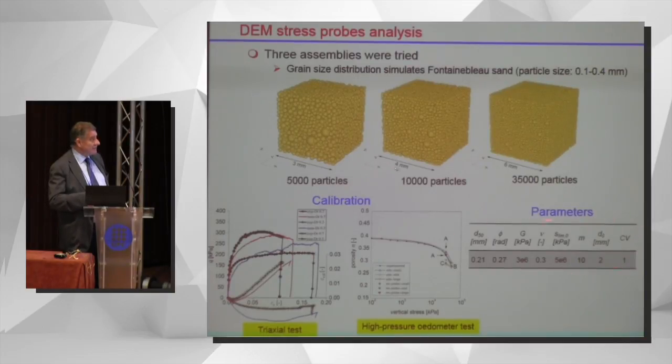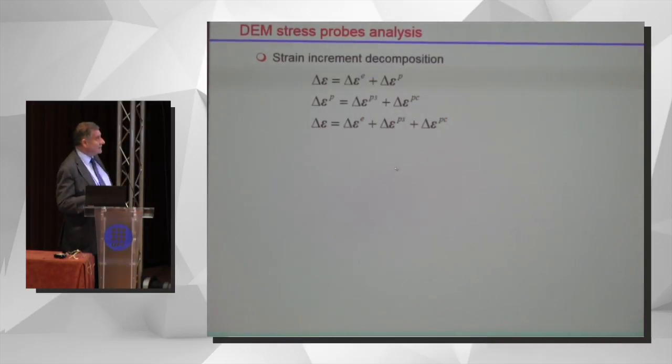So these are the parameters. There are not many. In fact, there are 6, because these relate to the size of the particles. These 3 parameters represent the contact parameters, and these other 3 represent the variation of strength with particle size. So that's all that has to be determined. We are in small strain plasticity.